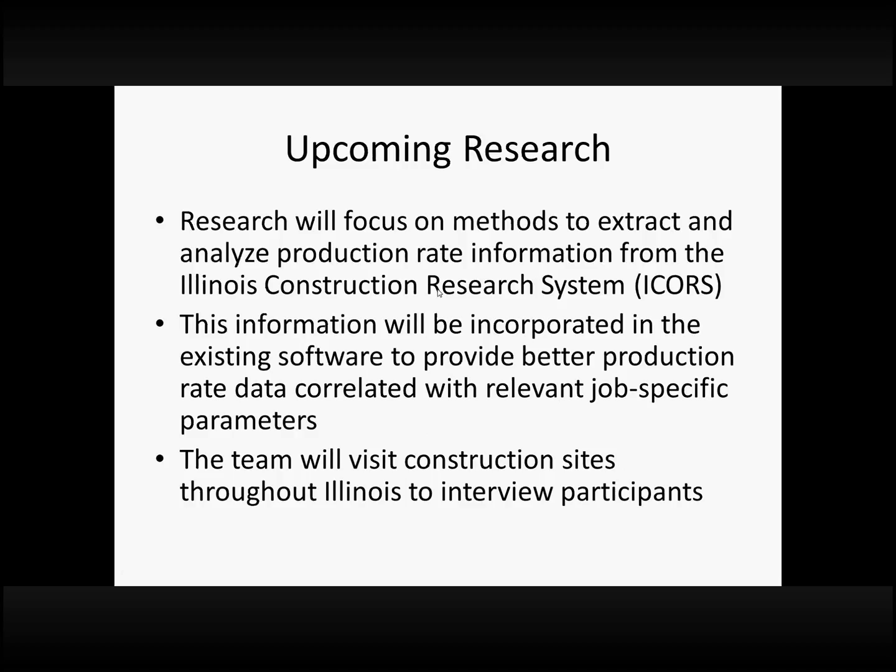The most difficult thing here is to really determine what is a production rate. Obviously the production rate depends on the contractor, how many resources they commit to it, and there's a lot of different types of activities. So what we plan to do in our next phase is to mine the data that's been collected over the last few years, a couple of decades, I guess, in the I-Core system, and try to synthesize that into better information based on historical data to help them determine expected production rates, based on things like the job size. Again, excavation: if it's a large job, you would have a much higher production rate than a small job because you would commit more equipment.